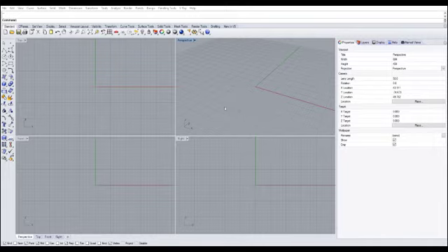The reason I had these on when importing my drawings from AutoCAD is simply because I do not have unreferenced layers, blocks, or line types. But yes, you should absolutely uncheck these items when you import your drawings from AutoCAD. Your model units and layout units should match, so make sure they're both in inches, and then say OK.